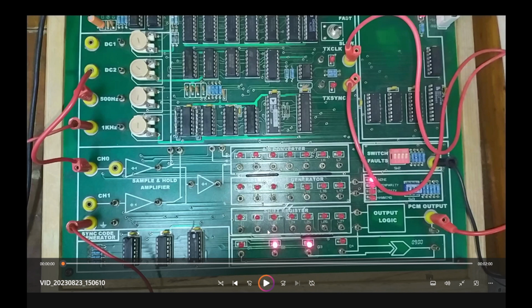So from the status LEDs you will be able to find the bit patterns that are being generated for the PCM code, and these are the clock signals. For measuring, you just have to slow the clock. There is a toggle switch. Initially this will be in the fast position, and during the waveform measurement this will remain in the fast position also. But as our eye can't detect the abrupt change of the clock, due to persistence of vision, in the fast position, if we keep the switch in the fast position, then what will happen?